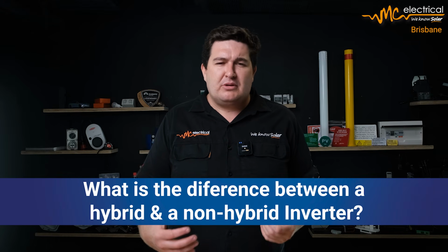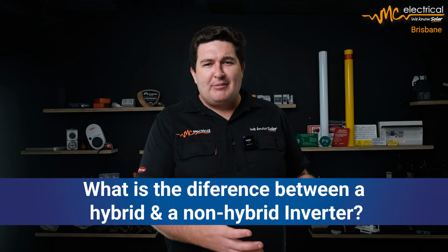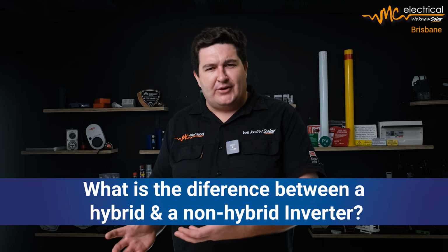Now you might say, well, which one's best? Well, realistically speaking, most systems installed in Australia are string inverters. These might include things like Fronius, Sungrow, SigEnergy. Microinverters are a little bit less common. They used to be more common, but when we're talking batteries now, generally speaking, a string inverter is a much simpler solution. Speaking about batteries, well, what is the difference between a normal or non-hybrid inverter and a hybrid inverter?